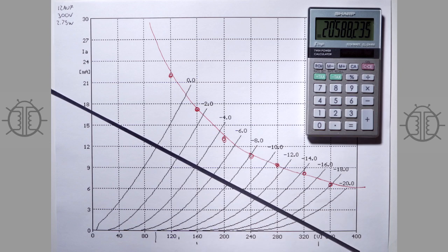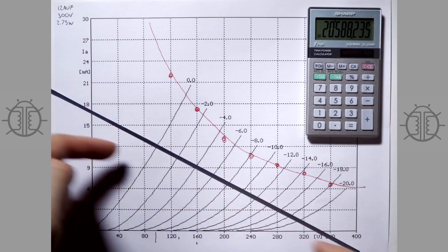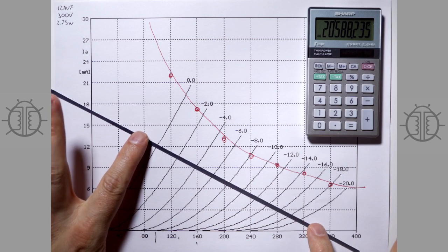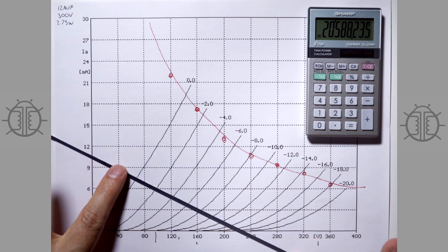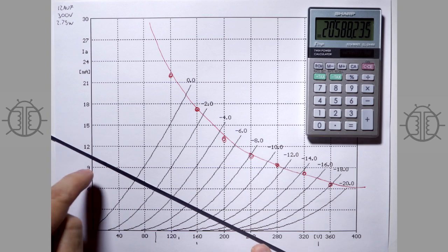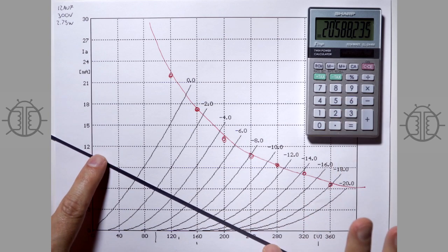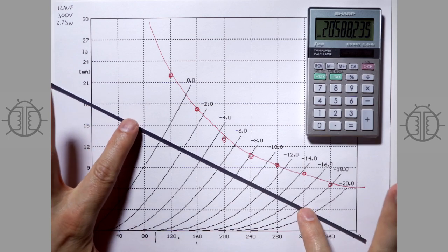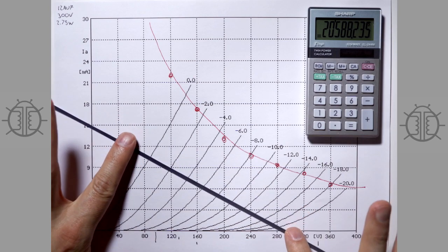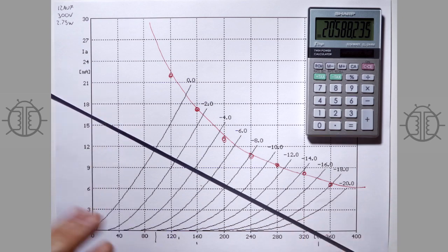And so here's a cool thing about this load line. The slope for our 20K is always the same angle. And so now, if we keep the same angle, it doesn't matter what we do. Like if we divided this voltage by this current, we'd get 20K. And if we divide this voltage by this current, we get 20K. And so as long as we don't mess up the slope of our load line, it's always 20K. And so that's pretty cool.